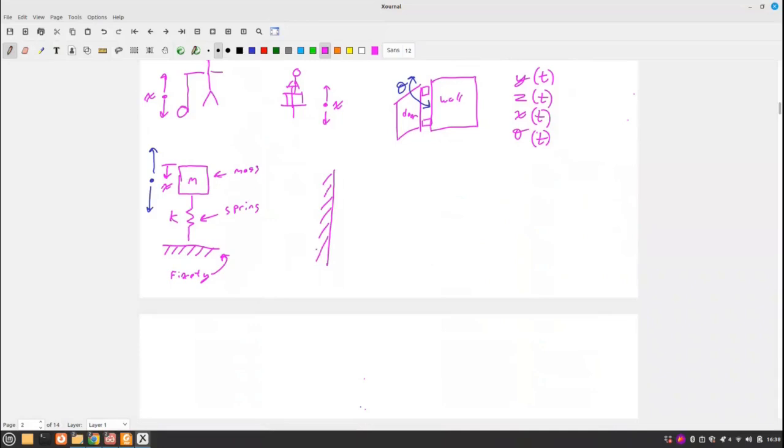Here I have a fixity. Here I have another fixity. And a fixity is just my edge of the system that's not going to move. I might have a pin moment. I have a massless rod, and then I have a mass at the end. And in this class, we're only going to do point masses. And this rod might be of a length L. And then over here, I have a spring. And now, well, let's draw that dashed. So it would move out here. And my degree of freedom is going to be theta as a function of time. And that's how that system will oscillate.